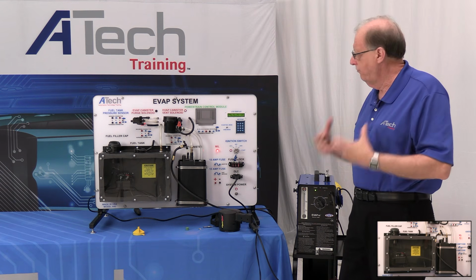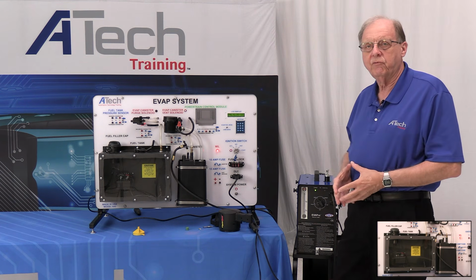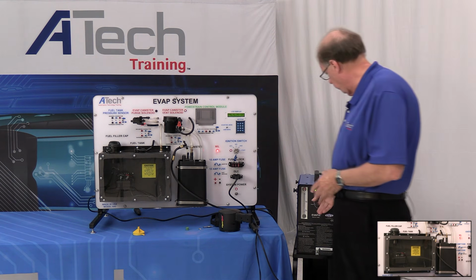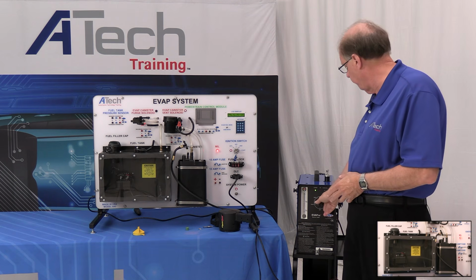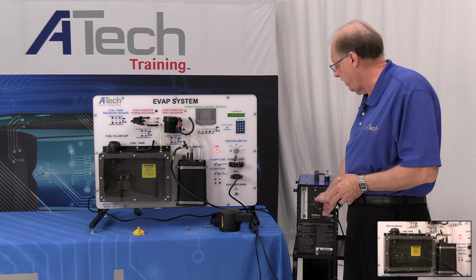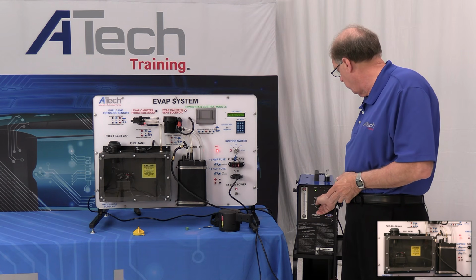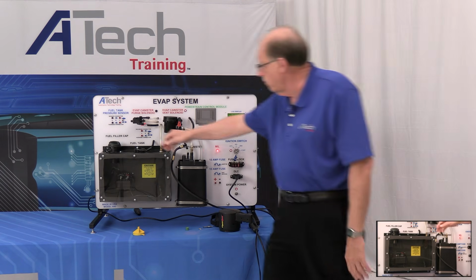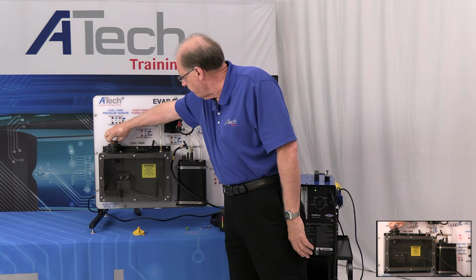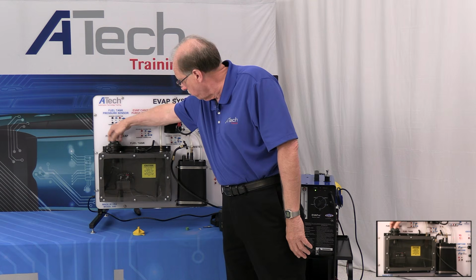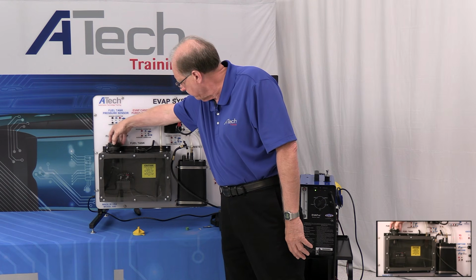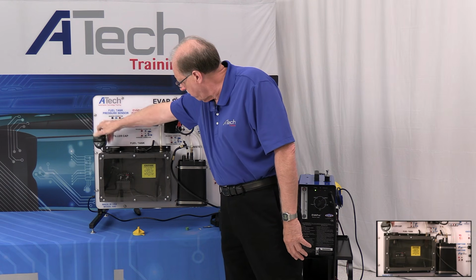Okay, if we're going to do a leak test with smoke, one of the things you think about, I just did the test up here because we did the test up here. I'm going to flip this thing over to smoke, all right? When I flip it over to smoke, what I want to do is go over and relieve the pressure in the system. You hear that noise that came out there? I'm going to relieve the pressure in the system, take this thing all the way off.